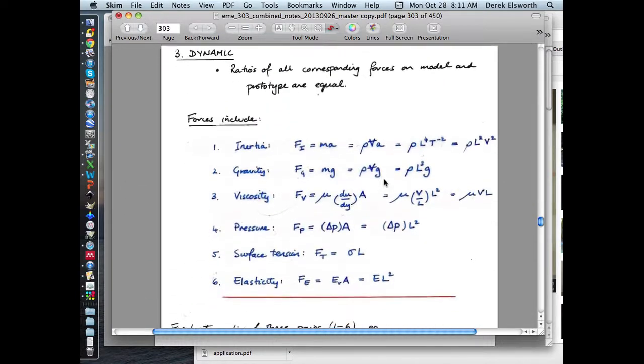But the other thing that we can think about is exactly what those non-dimensional numbers might be. So what we've done is we've used the Buckingham Pi theorem to calculate what those dimensionless groups would be. It turns out that if you define different dependent variables, so in other words, change in pressure is equal to viscosity, density, velocity, etc. If instead you write that as velocity is equal to change in pressure, density, viscosity, you'll get apparently different groups.